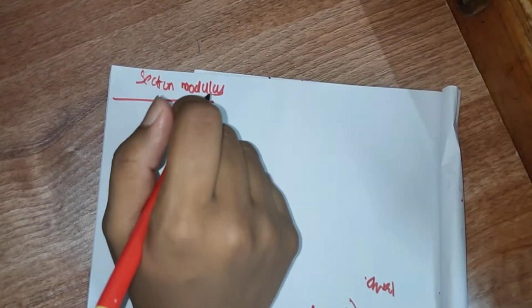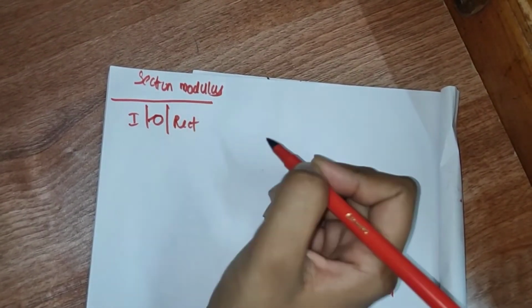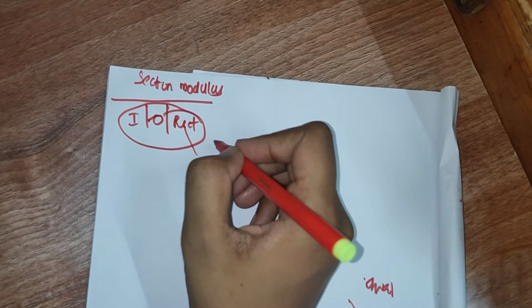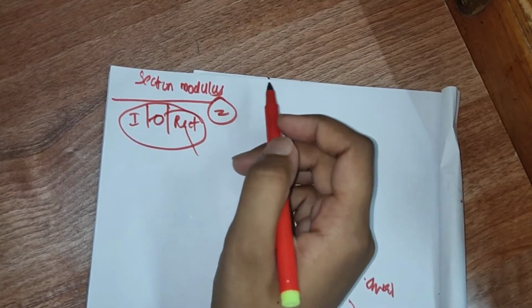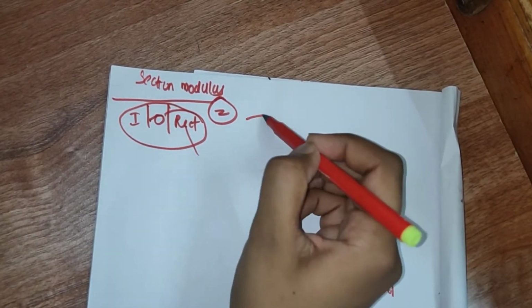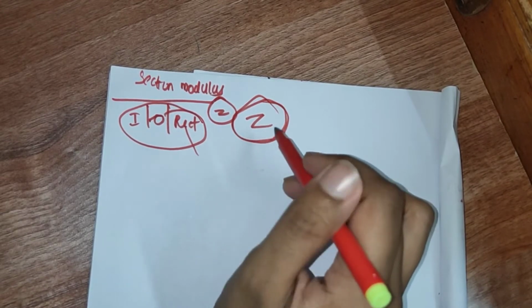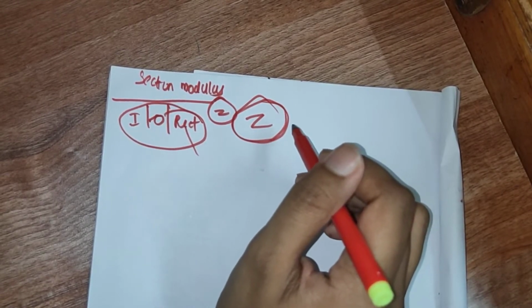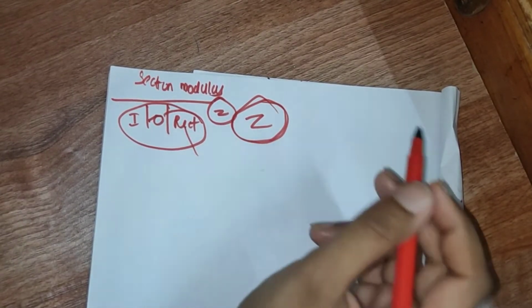So if I am having a high section, circular section, rectangular section, and I want to know which one is stronger, for knowing that I want to calculate the section modulus of all of these. Then we can see which is stronger. So while designing this, maximize the strength. To get the maximum strength, the section modulus should be maximum. Okay, so first we can find out the section modulus of various beam cross sections.